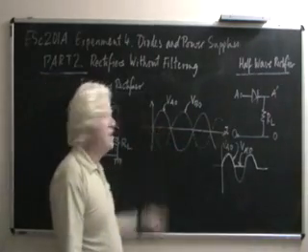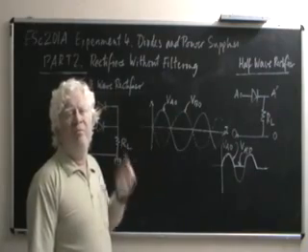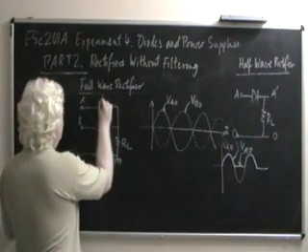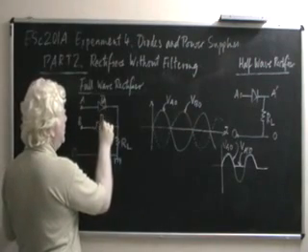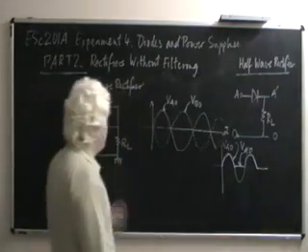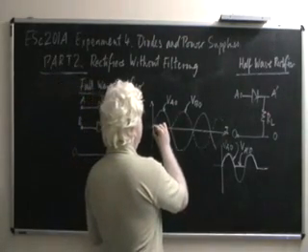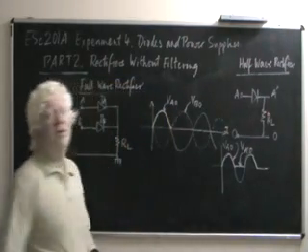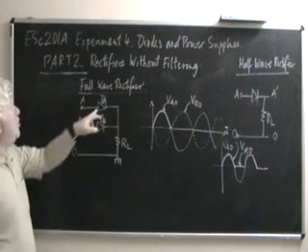In one half of the cycle, the terminal A is positive with respect to O. At that time, this diode turns on, which I will call DA, and this diode is off, and this diode I will call DB. So, at the output, across this load resistance, you will see a waveform that goes like this. What happens in the second part is that this diode stops conducting.